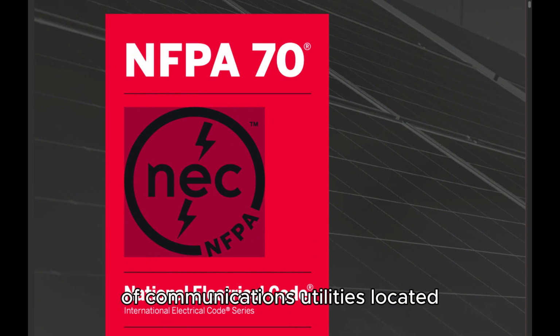3. Installations of railways for generation, transformation, transmission, energy storage, or distribution of power used exclusively for operation of rolling stock, or installations used exclusively for signaling and communications purposes. 4. Installations under the exclusive control of an electric utility where such installations are located in legally established easements or rights-of-way, or are located by other written agreements either designated by or recognized by public service commissions, utility commissions, or other regulatory agencies having jurisdiction for such installations.